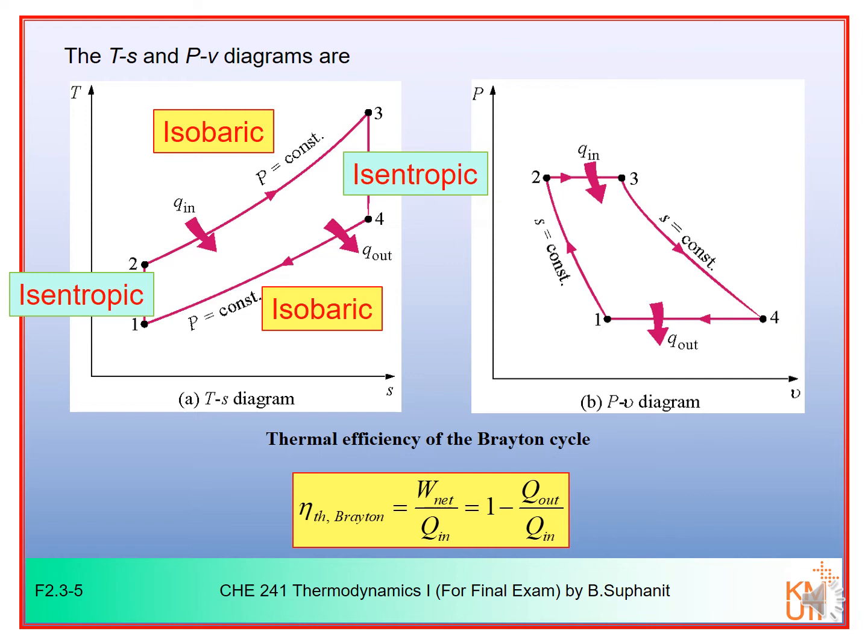On PV diagram, the process starts at point 1, then follows an isentropic line to point 2. After that, it moves along a horizontal direction in an isobaric heat addition to point 3. Then, another isentropic expansion as in process 3-4. And finally, closing the cycle with isobaric heat rejection in process 4-1, as shown in another horizontal line on the PV diagram.